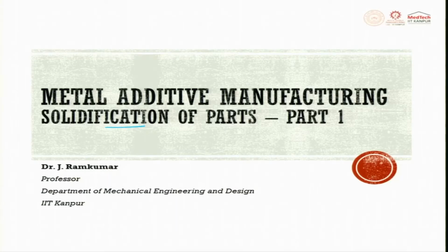Now, moving ahead, we will have to study some of the science behind the process, which will help us understand how to produce sound quality output. So, here we are supposed to understand the process of solidification. Solidification is a major principle which occurs during metal additive manufacturing. Because of this solidification process, you have residual stresses, microstructural changes, and also shrinkages. If you want to compensate for all these things, you have to better understand the solidification process.